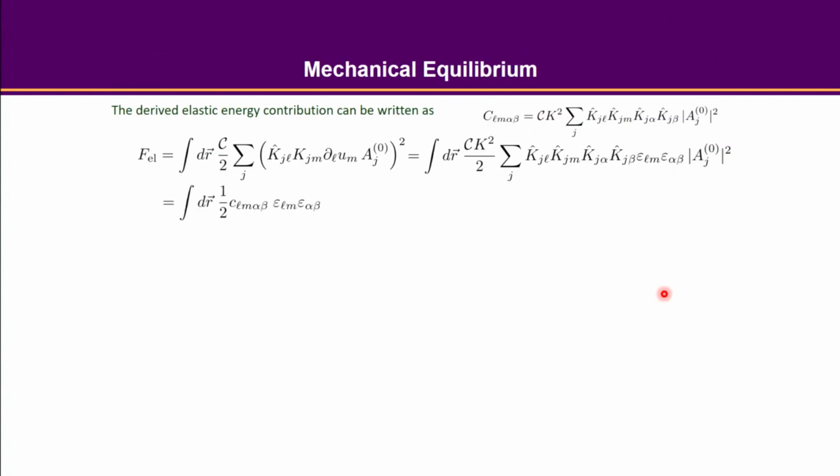Okay. So either from PFC or from the density functional theory using the amplitude expansion, you're always expecting the free energy can be rewritten as 1/2 the stiffness times the strain squared, right? So you can rewrite that strain stress relation as 1/2 of the sigma epsilon.